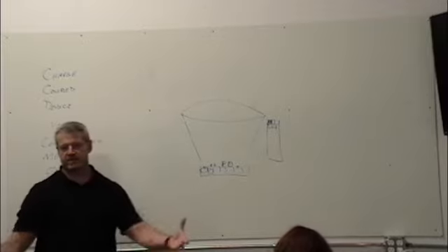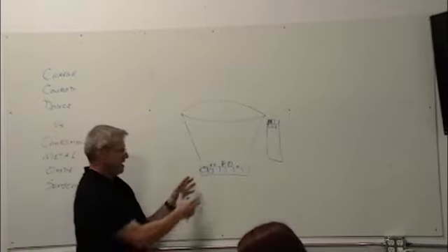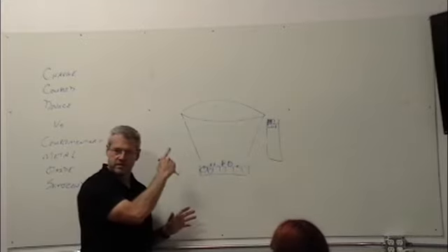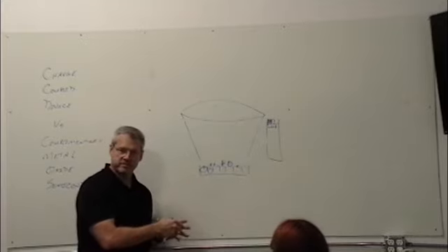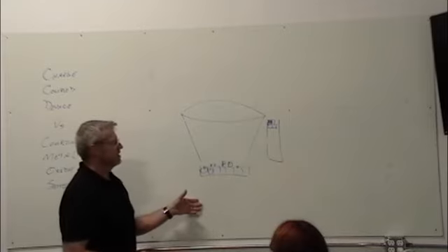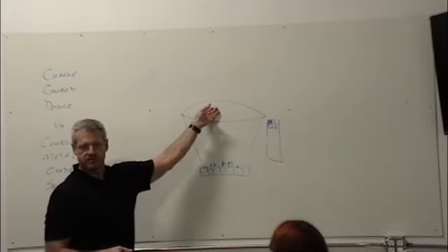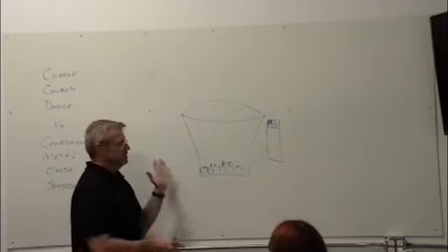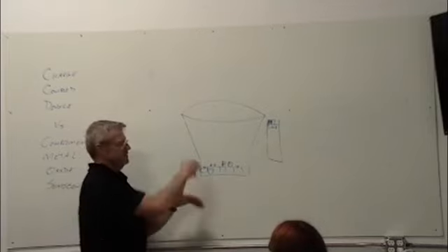And I basically optimize now. If I do bigger pixels, I'm losing information. If I do smaller pixels, I'm oversampling, and now I'm wasting money on this mirror, this camera system, and bandwidth. Yeah, there's all of that. So your optimum point is where it's a one-to-one match.